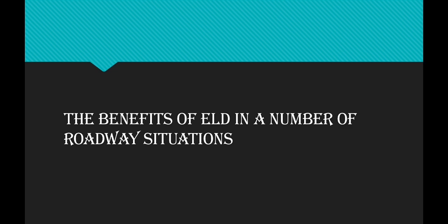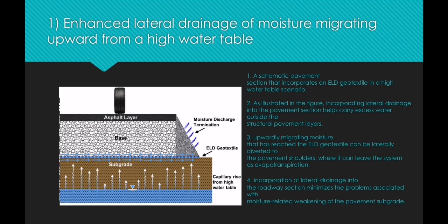The benefit of ALD in a number of roadway situations. First, enhances lateral drainage of moisture migrating upwards from a high water table. First, a symmetric pavement section that incorporated an ALD geotextile in a high water table scenario.